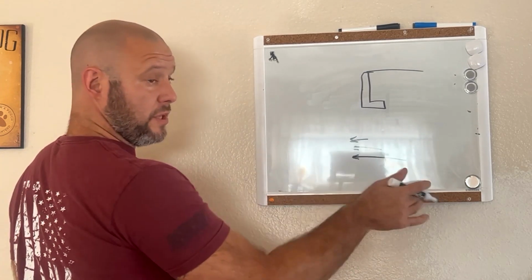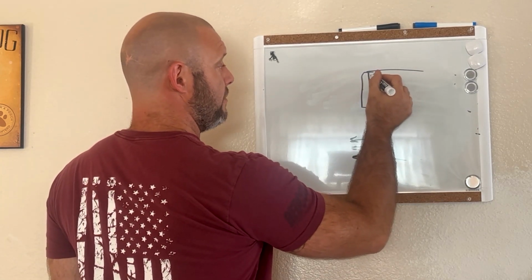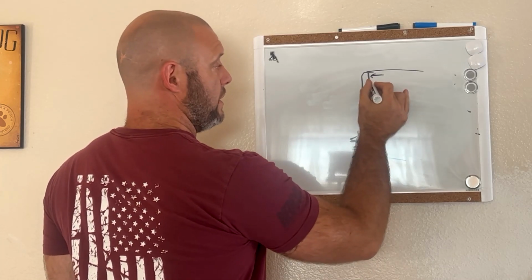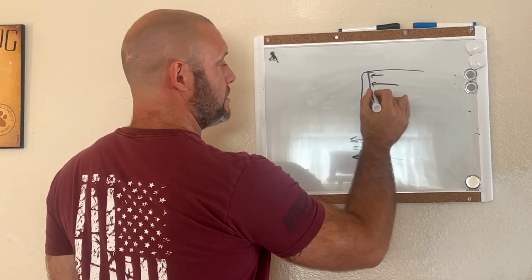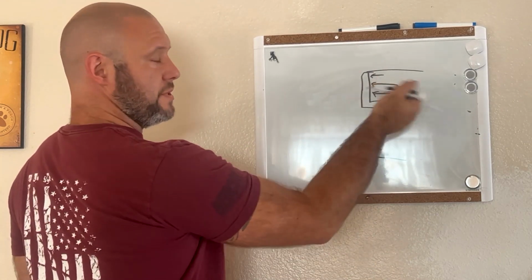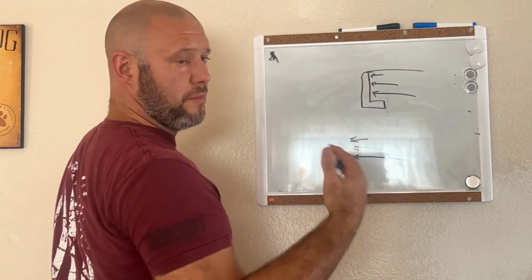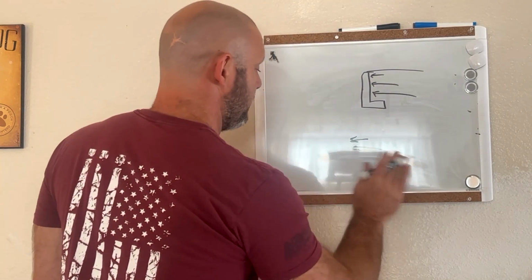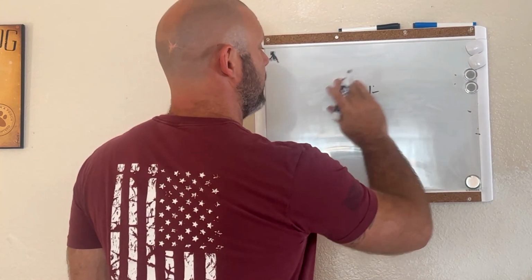And that's what it would look like. So up by the surface, you'd have some force laterally, then more force laterally, then more force laterally, pushing onto this retaining wall yonder, and the lower you go, the more force that you have, right? And that's an important concept for what we're going to go through.